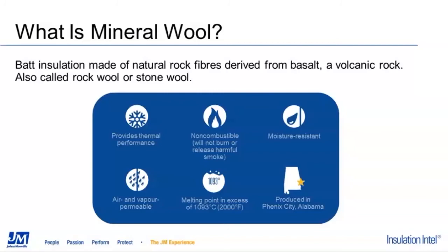That typically leads to why this is so popular in commercial applications as opposed to residential applications, where you have multi-story construction, many inhabited floors, large buildings where fire performance is critical. And that's really where mineral wool excels. It has a much higher melting point, as you can see on the screen, much higher than fiberglass does. So it's really about preventing the spread of fire from room to room and from floor to floor in case there was a fire event.